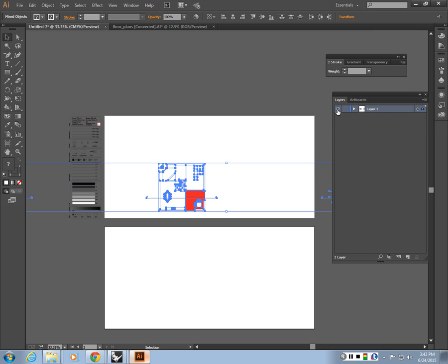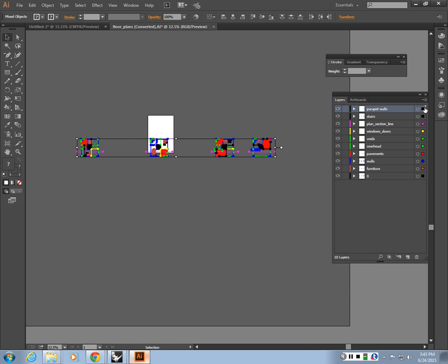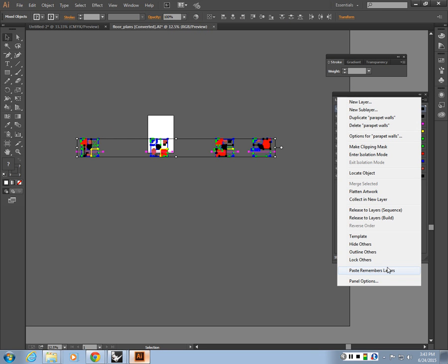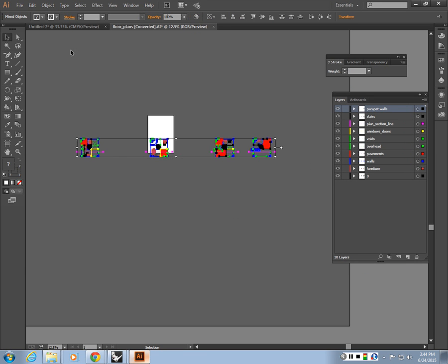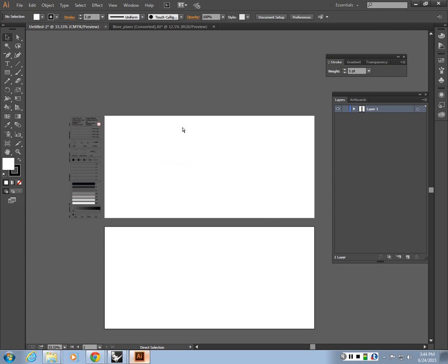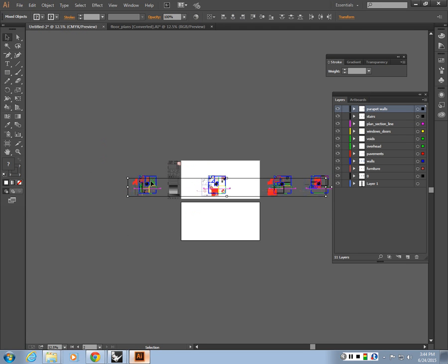And you will have a hard time selecting those objects on different layers to give them line weights. So if you're not seeing the layers, you need to choose Paste to Member Layers option under this drop down. Okay? So choose this one, then choose the objects, Control C, Control V. Now my drawings are brought in to my layout.